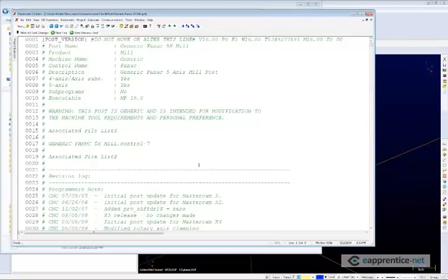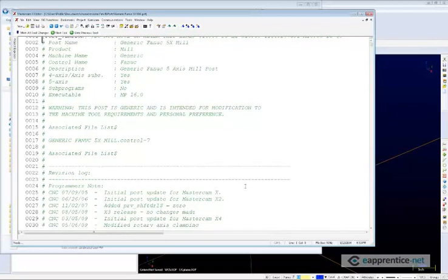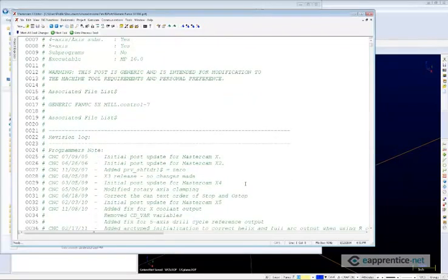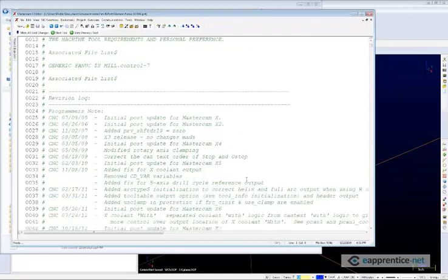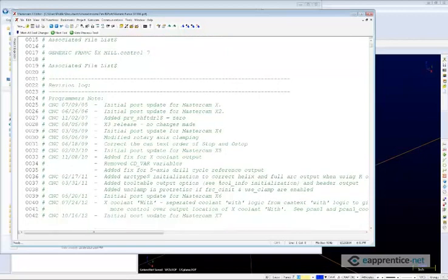So one of the nice things about this is that your Mastercam software comes with a free 5-axis post processor that can be configured for just about any machine type. So literally this one post processor that I'm looking at right here, we can make multiple copies of it, and we can set it up for a head-head, a gantry style machine. We can set it up for a table-table, a trunnion style machine. We can set it up for a head table where one of the rotary axes is on the head, one of them is on the table, something like the DMU.